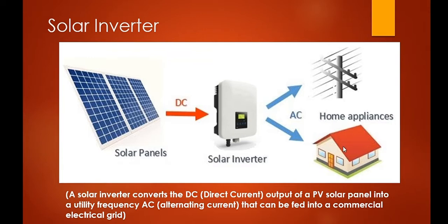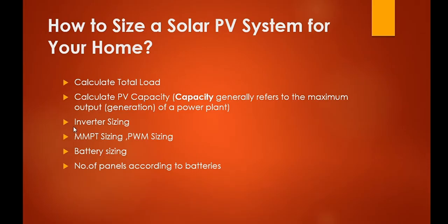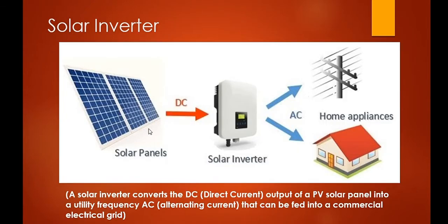I hope you understand the function of a solar inverter, and why we need to size the inverter. Next is the charge controller. There are two types of charge controller. One is the MPPT and the second is the PWM. MPPT stands for maximum power point tracking, and PWM stands for pulse width modulation.